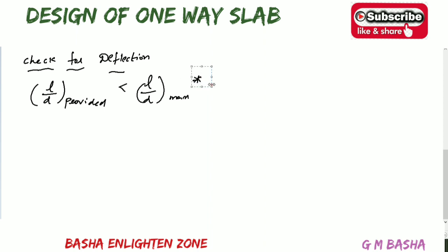First, what is the L by D value we provided in our slab? You can simplify that one. So what is the L by D value? L value will be equal to 3120 and effective depth will be equal to 120, which gives 26 here.